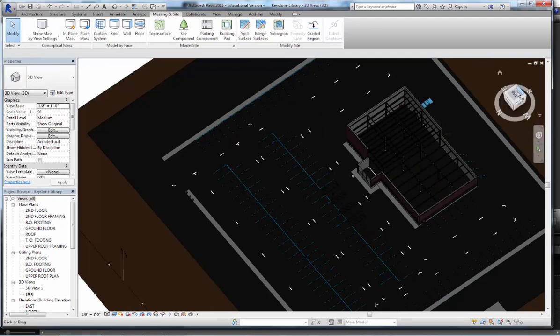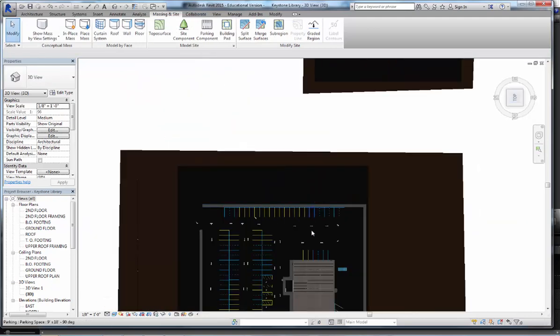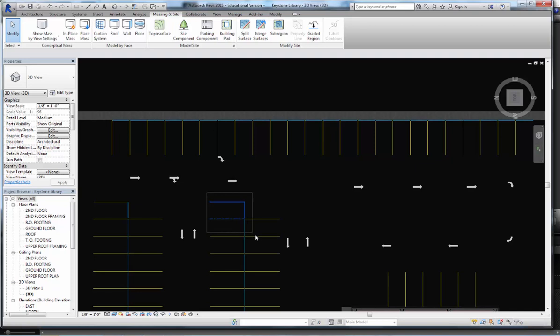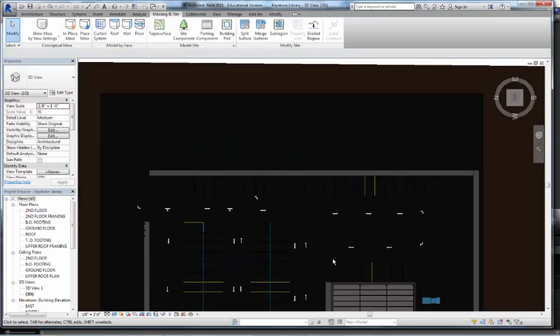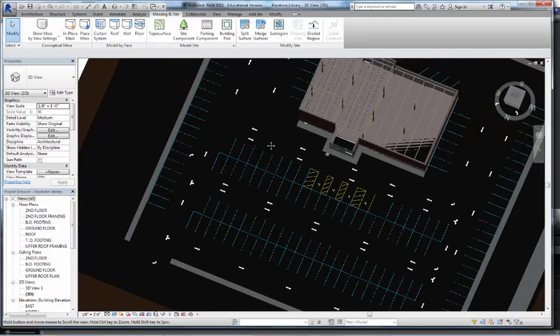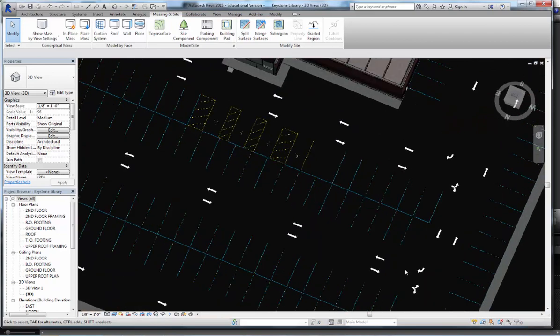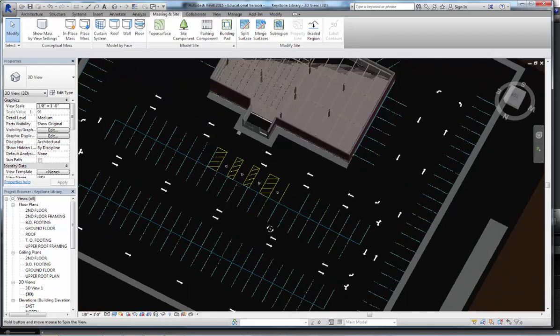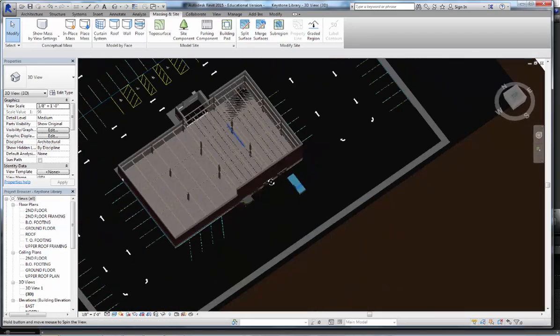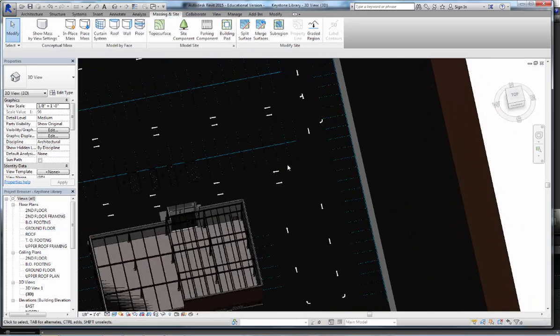And the cool thing about Revit, don't forget, is once you place a couple parking lots, you can actually just copy them and then paste them, and then maybe you have 2, and then you have 4, and then 8, and then you can really speed up this process just by copying it every time you go. So definitely do that to speed up on time. Also, when you're putting in your spaces, try to think about the flow of traffic. How is traffic going to flow in your parking lot? If you don't have a flow, cars are just going to look for whatever parking space is available and try to get there however possible.